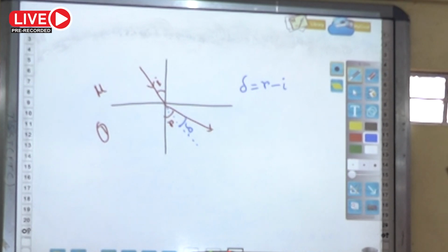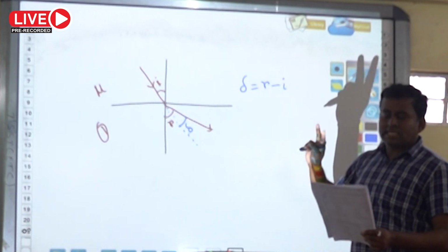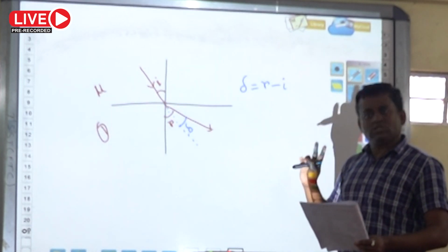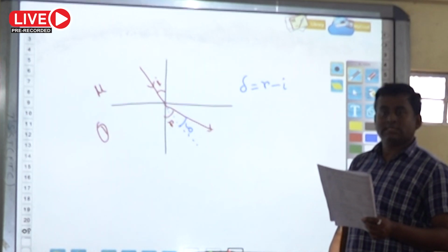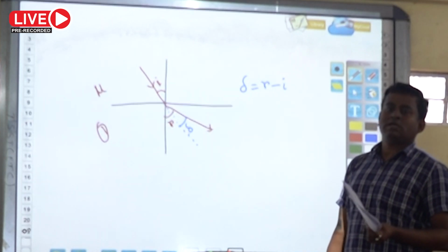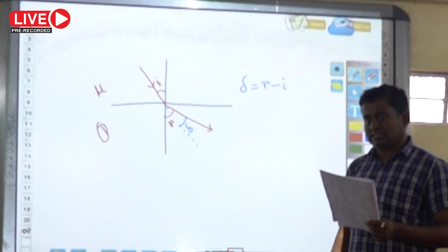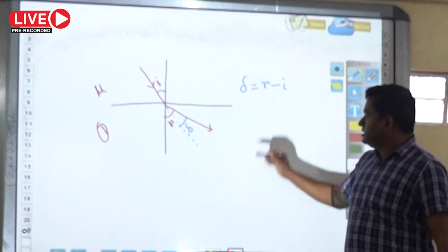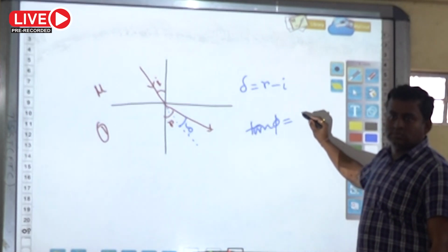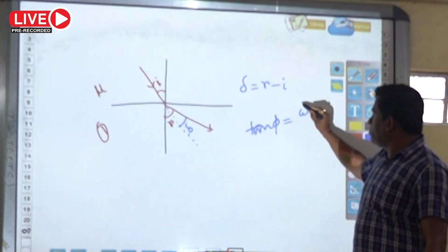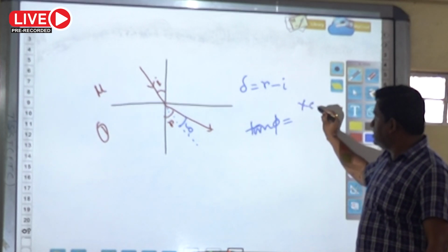See, resistance is 1 kilo ohm in both the options. Resistance and C, these two are present. That is confirmed. Now, two options have a resistance and C combination. Then you have to find out the value of C or resistance. Now, check, both the options have the same resistance. So you have to find out the value of C. That means tan phi equal to 1 by omega C, that is XC by R.